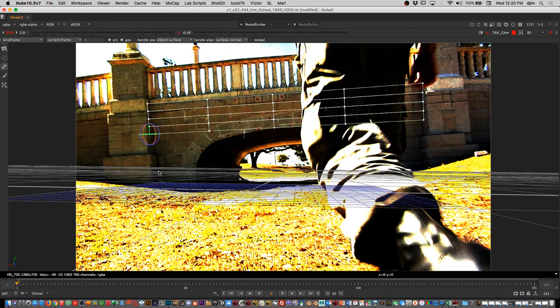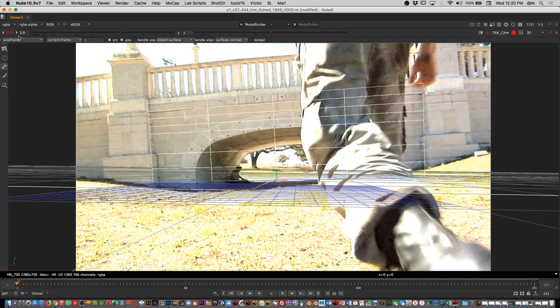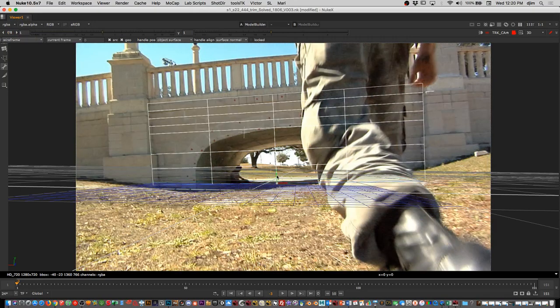The same idea as before. So let's go ahead and just do some quick extrudes. So let's take edge selection, and let's select the edge that we want to extrude. Let's say I want to extrude all these, doesn't matter. We're going to hit enter, extrude it down, right about there. Enter again, extrude it down, enter again, extrude it down. Just reset this back very quick. Alright, so I'm just going to make sure that everything is extruded the way that I need it.